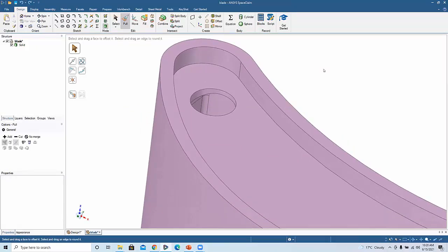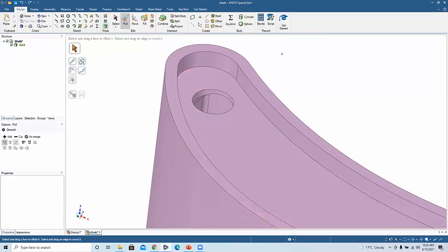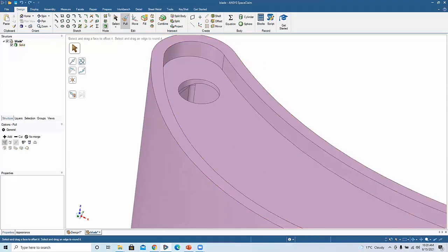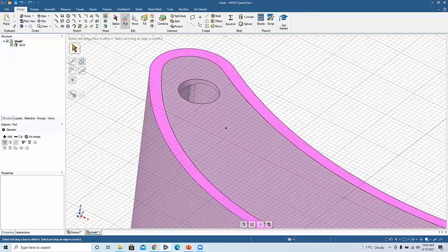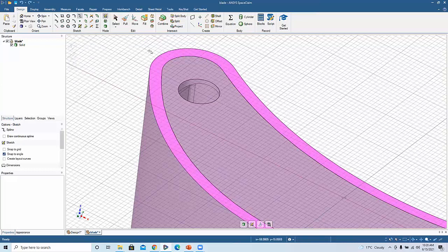Another one that a lot of people ask us about is nonlinear slots. If I wanted to create a nonlinear slot, say, for example, I wanted this slot to follow the track of the top of this turbine, what I could do is create a driving geometry section on top of this face. I'm going to sketch on top of this surface and click on the spline tool. Because I've selected the face where the hole exists, if I hover over the line of where the hole is, all of a sudden the vertex of the axis appears. Now all I need to do is click on the vertex of this axis and select where I want to place this spline.